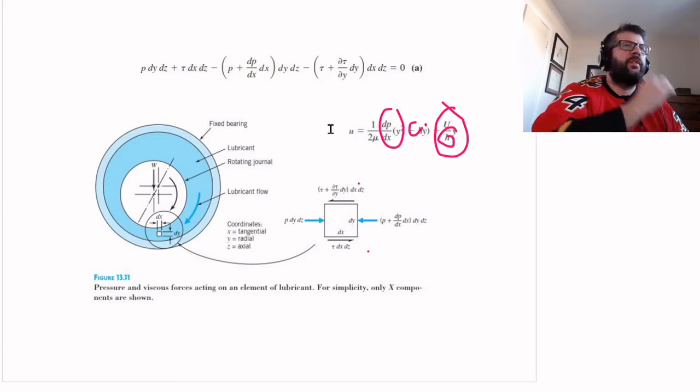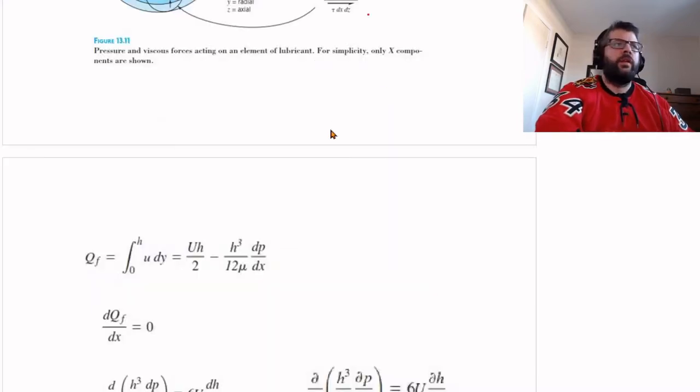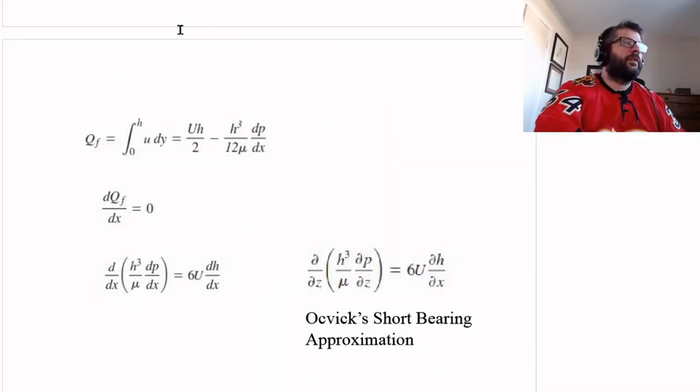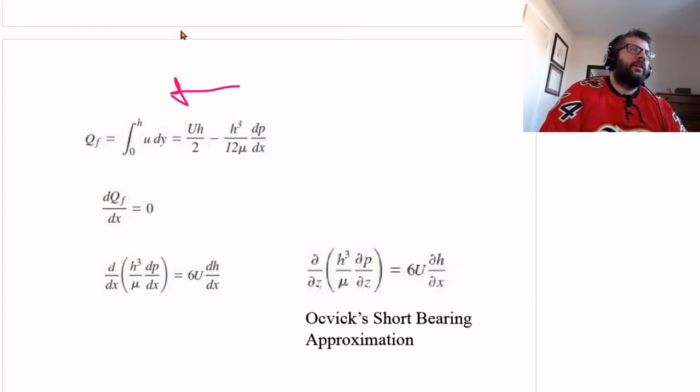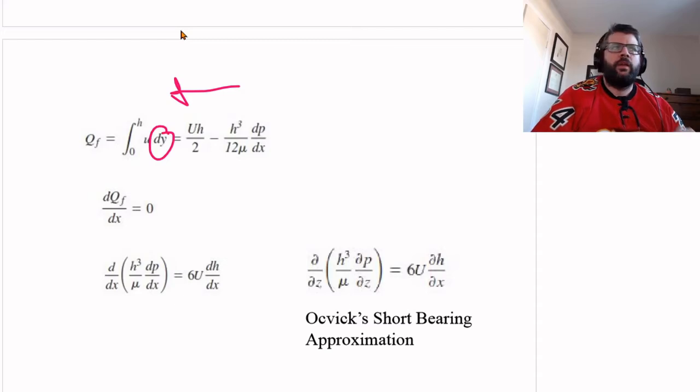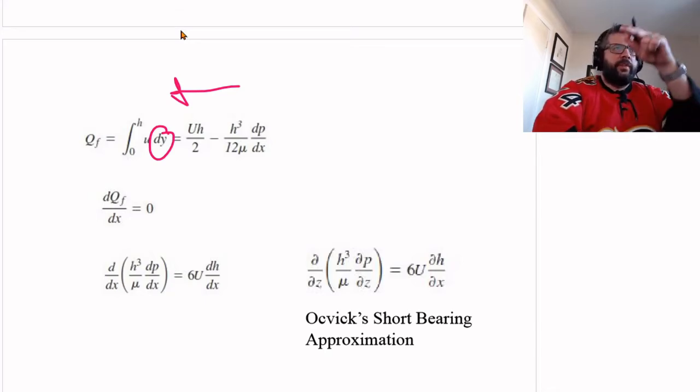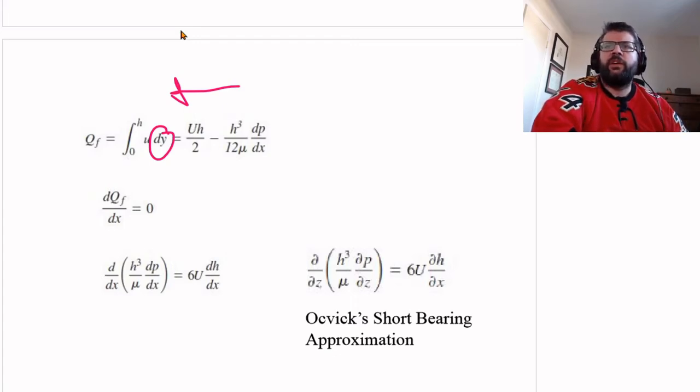So if we have the velocity kind of in that direction at any point, well, we can figure out what the flow rate is, because basically we've got that flow rate, got the velocity moving in a particular direction, and then taking that, multiplying it by a height term, and integrating from the bottom to the top allows us to solve for what the mass flow rate will be.